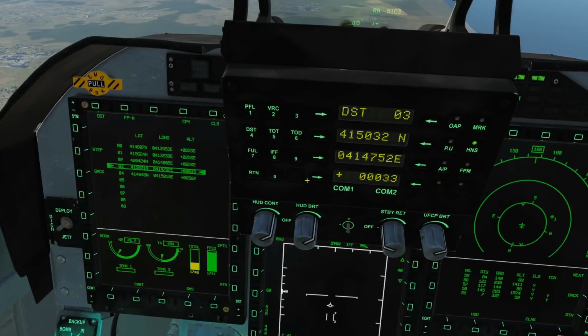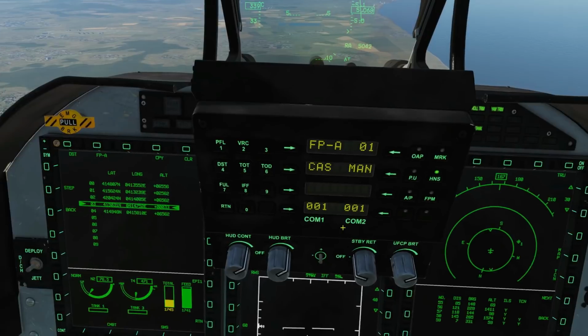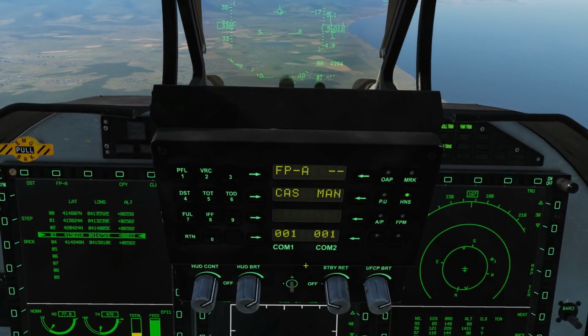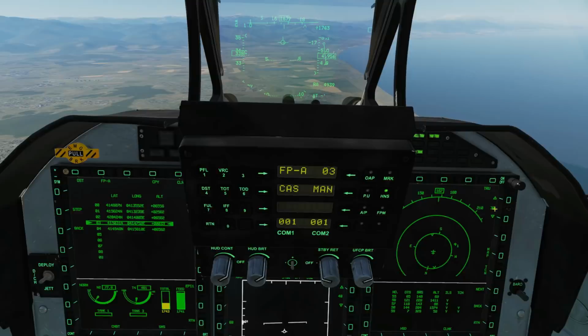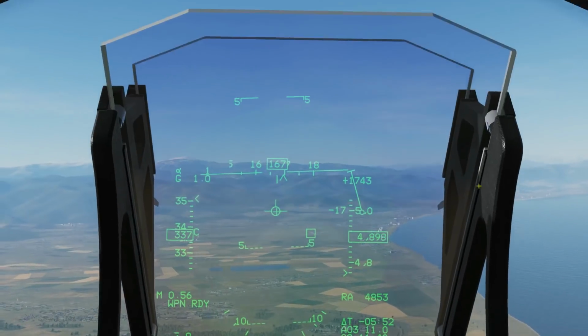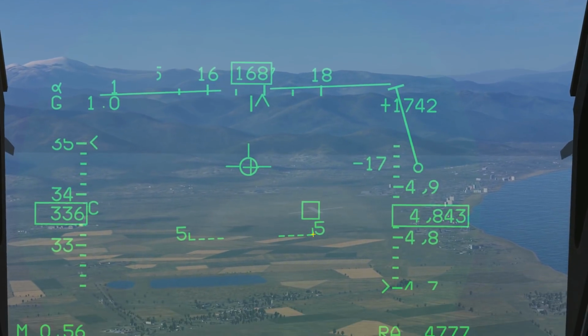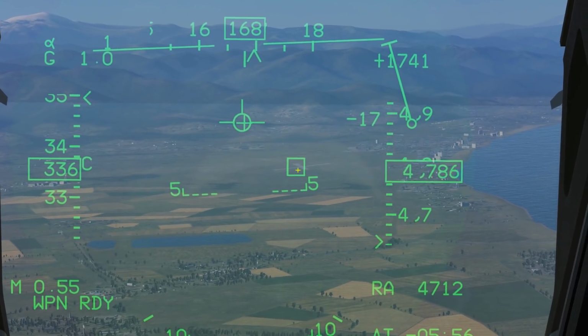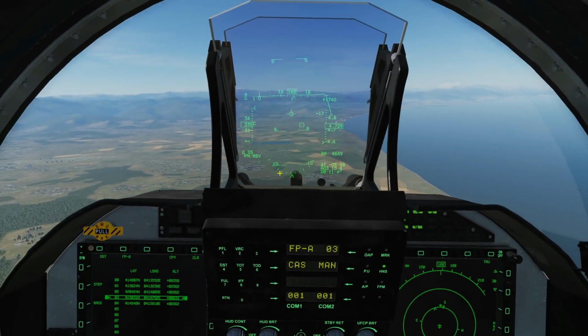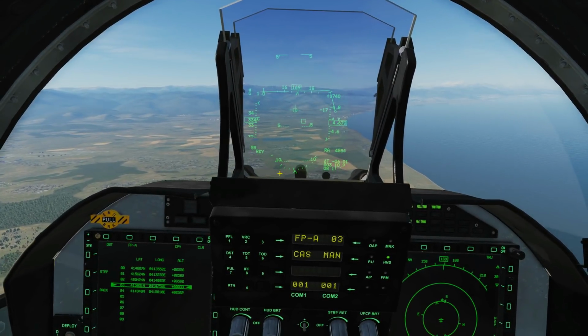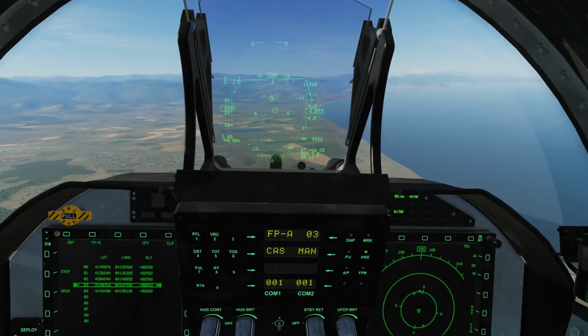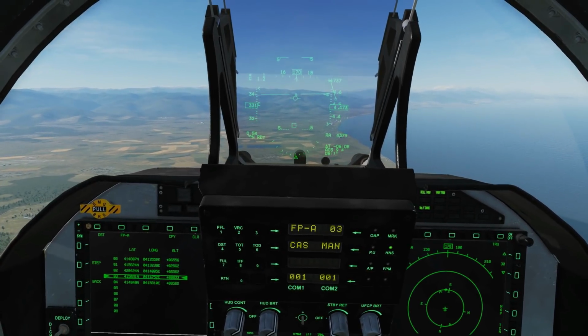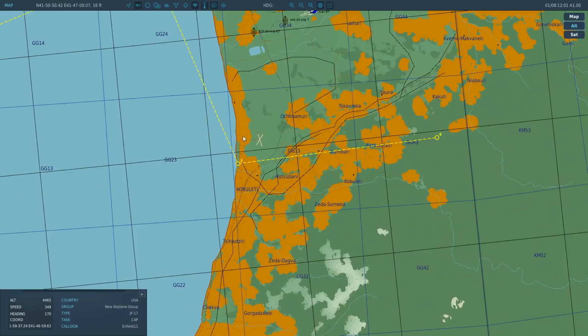That's no good. So what we're going to do is back to main menu. We're going to click here, increment, increment, let that settle. And you can see now it's got waypoint 3 now selected, which of course is moved into the middle of the cross. So that is how we manipulate a waypoint from northings and eastings. So there are other ways of doing this. Next, I've decided I don't want waypoint 4 out here, it's useless.